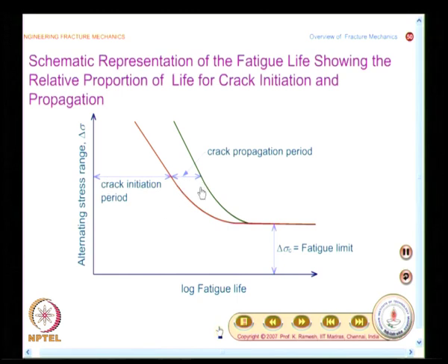So, you really take an advantage if you delay the crack initiation phase, and this is what metallurgists focus upon. They find out methodologies by which crack initiation can be delayed. In fact, if you have blunting of the crack tip, it would delay the crack growth.